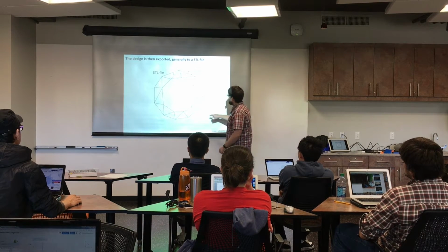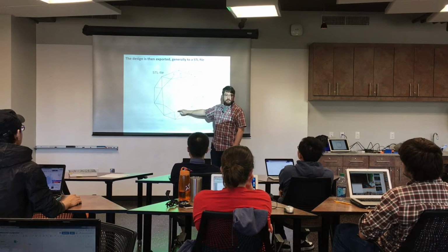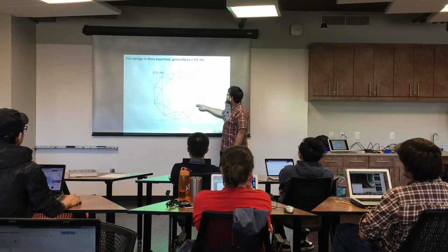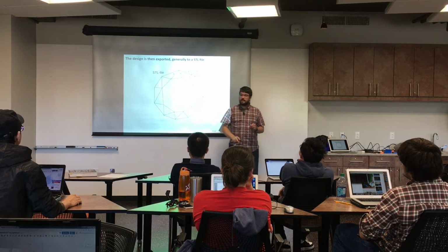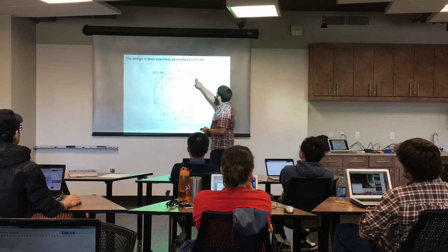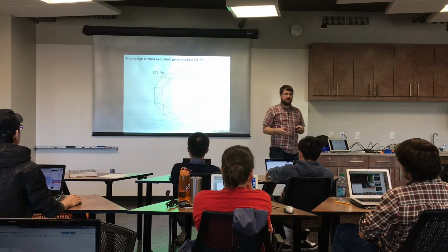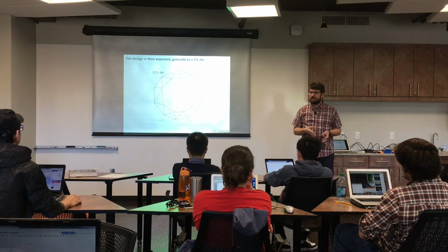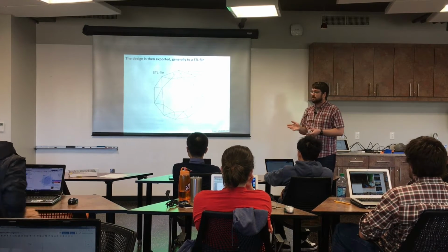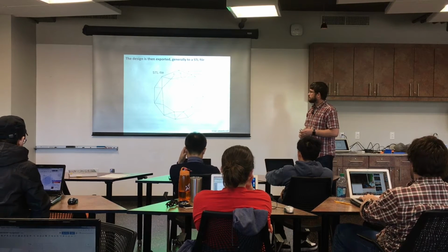So say your CAD model, these two red dashed rings, so we have like a cross-section of a tube here. The STL file will not perfectly reproduce that because it is tessellating, right? It's meshing. So you can see here, well, it's a bunch of flat sides that are approximating a circle. So you have to export at an adequately high resolution with STL, otherwise your part will be very angular and not at all what you expected.